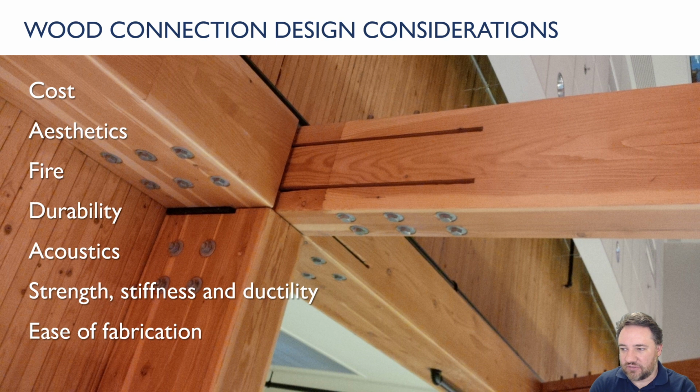So that's another benefit often of using these concealed connections, because believe it or not, heavy timber is pretty good in fire because it takes quite a long time to burn through a very big, thick timber member. So sometimes concealing the steel plates, like shown here, actually gives a benefit for fire design as well.